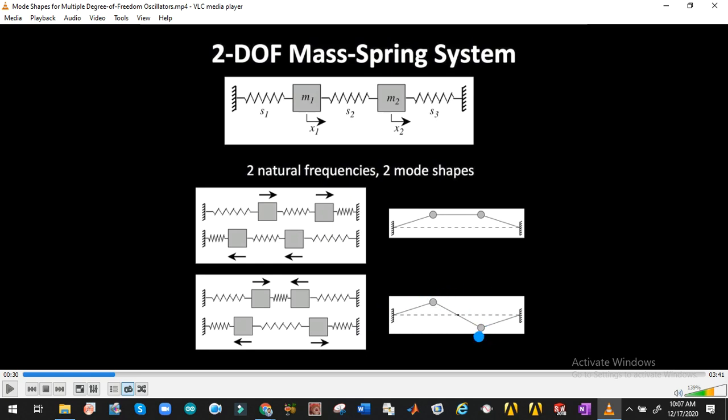Now according to the analytical description, we have observed that if we are going to avoid maximum amplitude of a particular mode, then we need to provide a support or a stiffness element at an antinode only. For example, if I provide some kind of support or stiffness element at a node, then it will have no effect.